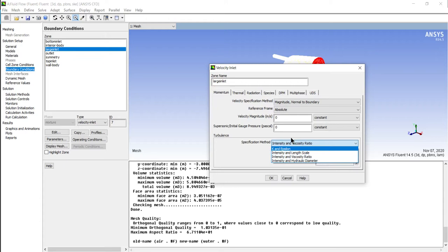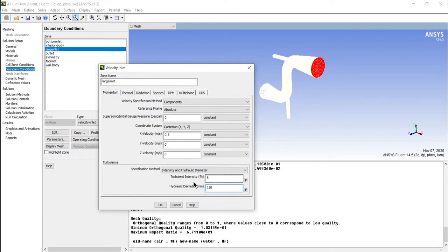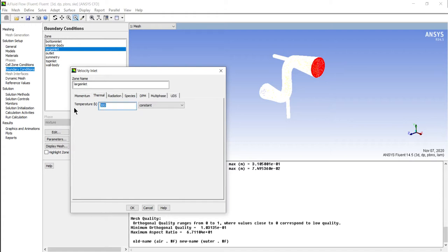With respect to what, I would have completed this before, I think 0.2 meter per second. If you want, you can make it 0.4 or 3 meter per second with respect to the diameter, 150 mm. So you should note that the unit should be changed while defining all these things, very important. The inlet temperature for me, it's 295, not 395, 295, that is room temperature value.